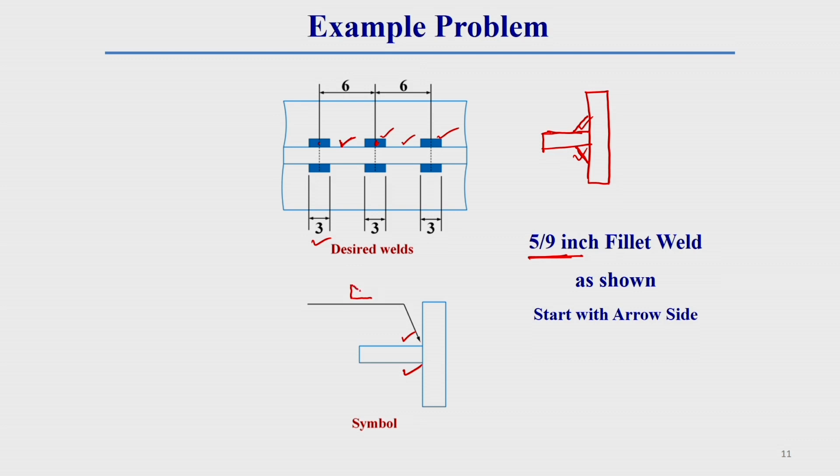It's a welding symbol that is triangular in nature, which means fillet welding. So it is a triangular shape. Both sides generally have fillet welding done, so both sides will have a triangular shape. Now the size of the weld is given, generally on the left side of this fillet weld symbol.